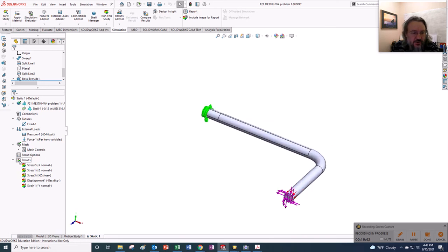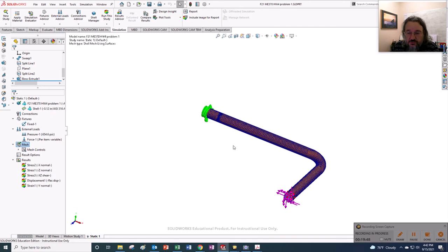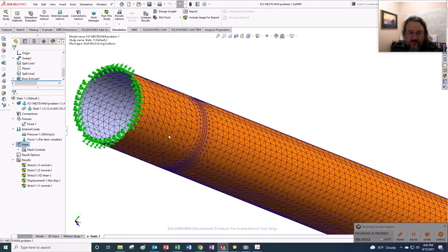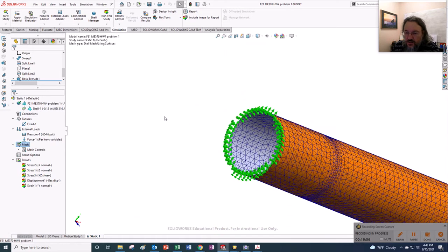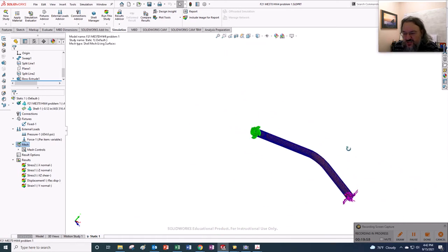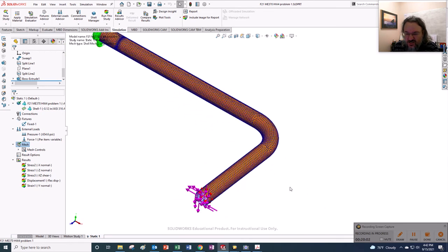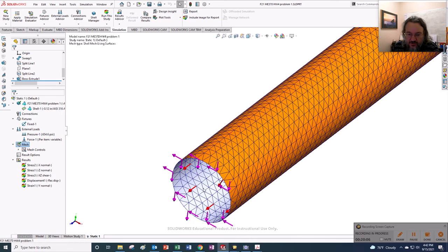Here I'll show mesh. Where's show mesh? There you go, show mesh. Okay, so I meshed it sort of fine right there, but you can see that these are actually plate elements. I don't think SolidWorks' plate elements are very good compared to maybe some ANSYS or Abaqus or Nastran, other FEA codes. I put the loads right here onto this edge.